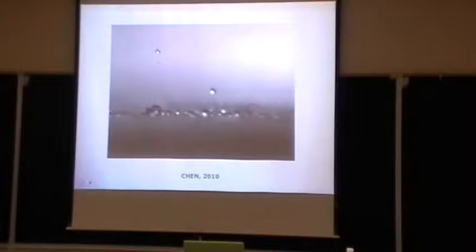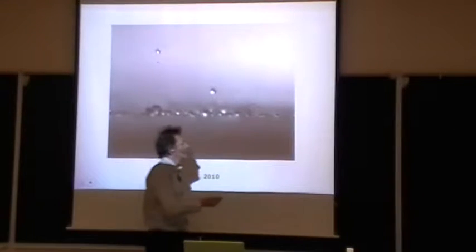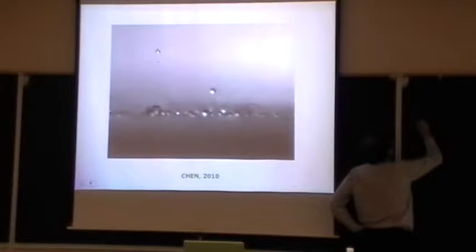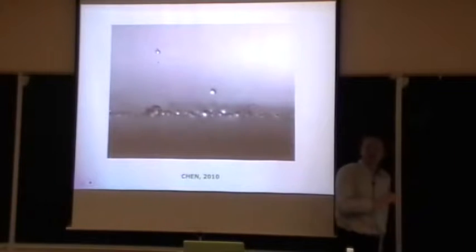And so, if you want to understand this phenomenon, you just write that, well, the typical energy that you gain there, which is the size of the drop, the surface area of the drop times the surface tension, was transferred in kinetic energy, rho v square r cubed, which is the most ideal situation that you can imagine. Of course, you can think of losses there, but I ignore these losses. You immediately find that the typical velocity at which this drop should take off is something like the square root of surface tension divided by rho r, which is a very interesting velocity. It's the inertial velocity when you think about surface tension phenomena.